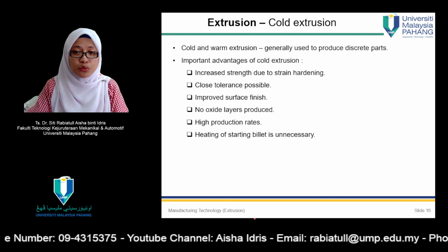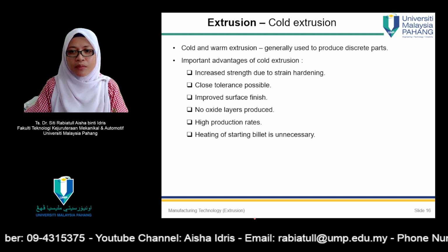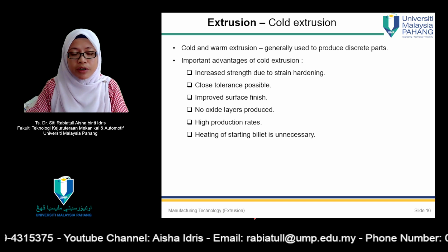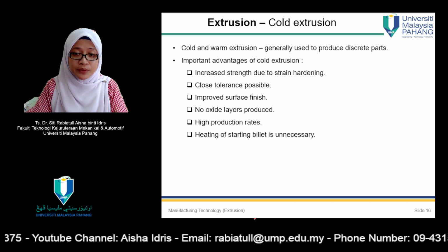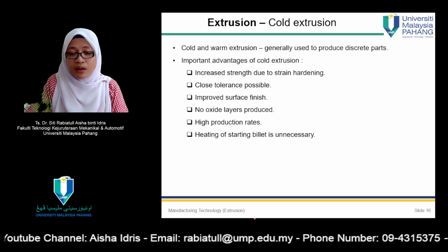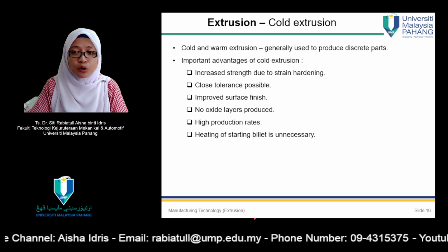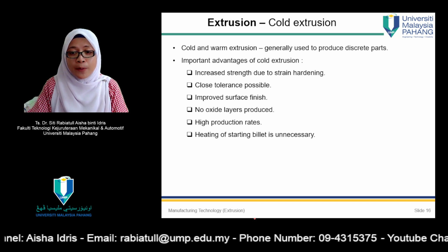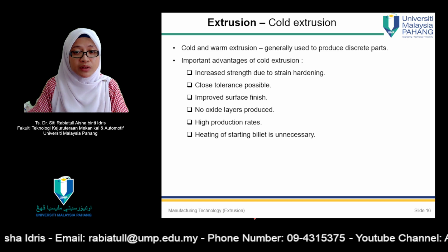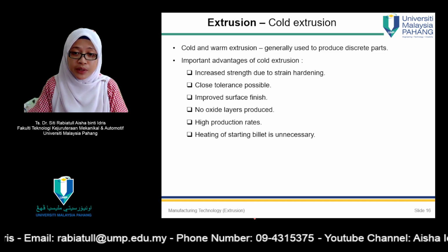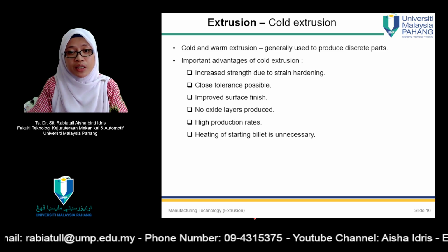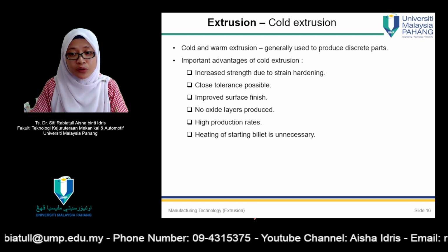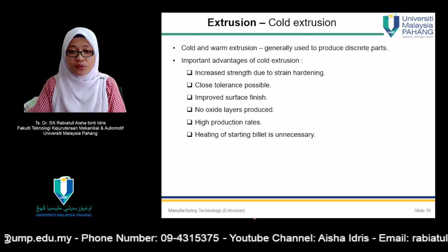Meanwhile, cold extrusion, or cold or warm, actually cold normally refers to a room temperature process. So the advantages of cold extrusion are no oxidation, high production, cheaper in cost, lower energy, higher strength due to strain hardening and so on and so forth.